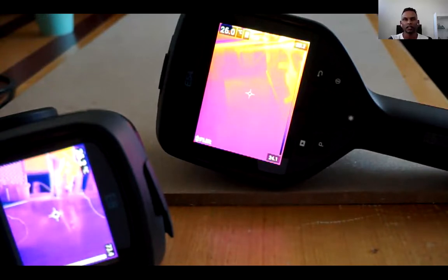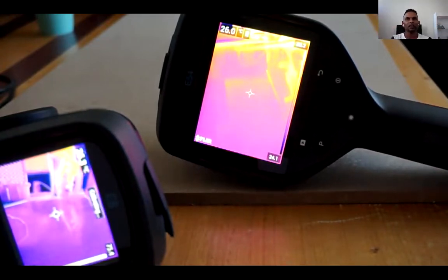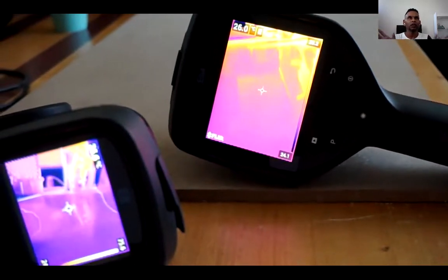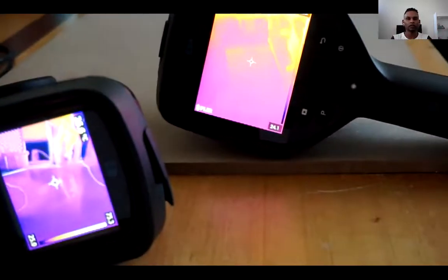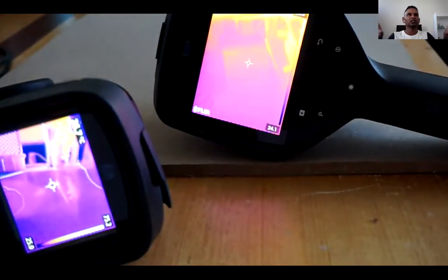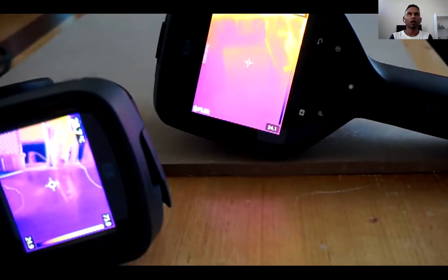So yes, resolution is important, and that's linked to field of view. Because you're looking at a larger area, you need a very wide angle field of view, so as I mentioned, 42 degrees. And because you're working with a wider field of view, resolution is important, because you're going from a narrow field of view to a wider one, so your pixels get spread out. So it's a combination of both. You need a wide field of view plus a high resolution camera.